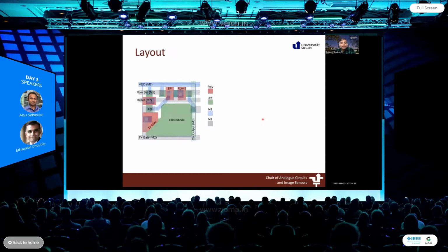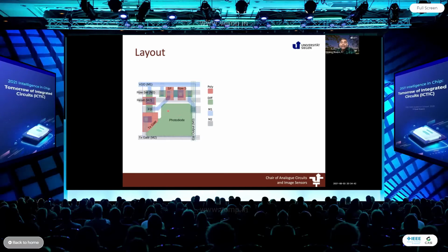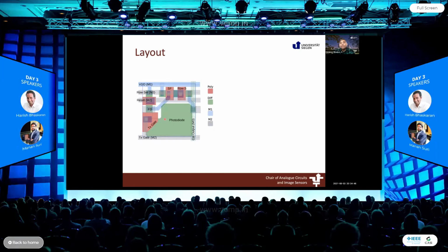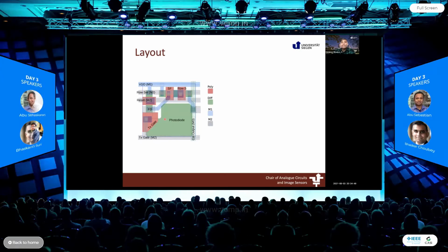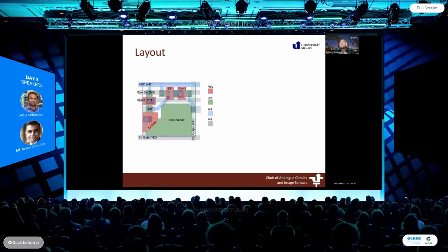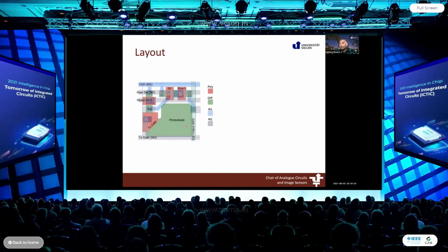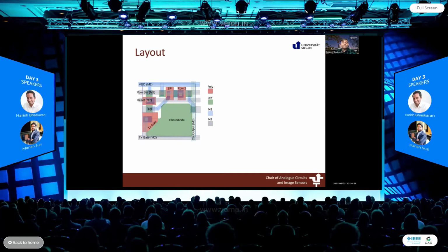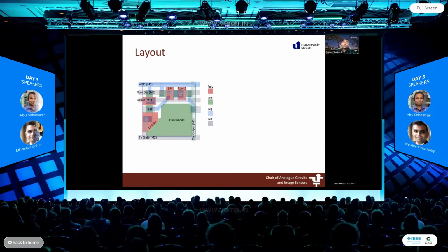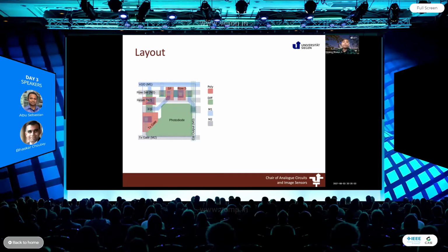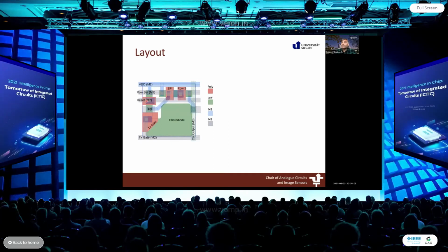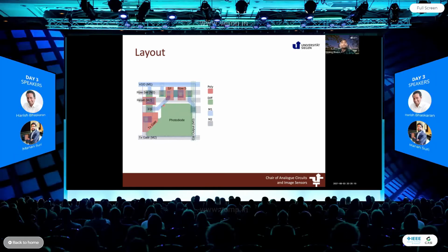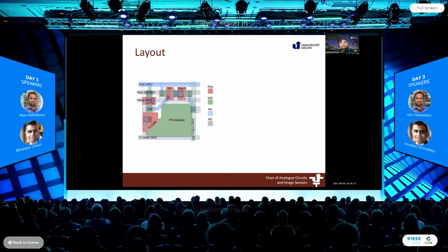When we design a pixel, our ambition is to have as large a photodiode as possible. If you look at the layout, we want a large photodiode to capture as much light as we can, because at the end of the day, it's an imager. So you want a large photodiode and a small area devoted to transistors, because that's not going to capture any light. If we could have a diode sitting on top of the pixel, that's perfectly fine. If we had 3D integration, that would have solved our problem. But as of now, we want the diode to take as large an area as possible.